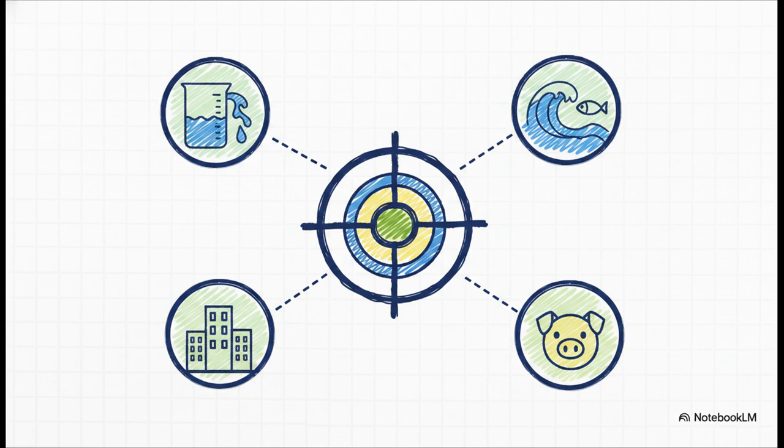There are a few nuances, though. Pig farms, for instance, have a provisional standard of 22 milligrams per liter until September 2028, but cow and horse operations, they've already moved to the general standards. So before you finalize any schematic, you've got to verify your facility's exact discharge volume and location. Plus, always double-check for local municipal add-on standards. They can sneak up on you.